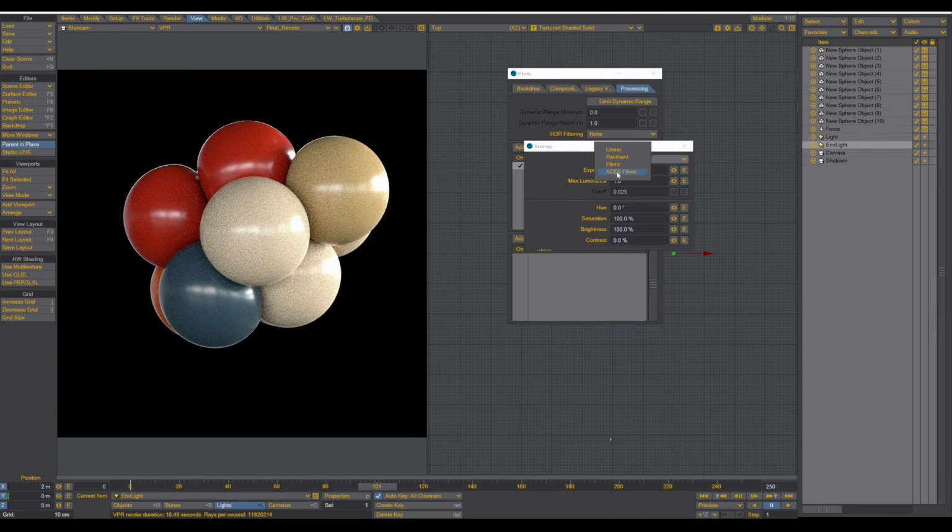When you use this, the render looks way more pleasing because you don't have these burned out highlights. But it's baked into your render, right? If you want to use the ACES workflow, don't use any of these tone maps. Just leave it as it is, with these burnt highlights, and export the animation or the render as an EXR, and then you can use the convert color spaces.